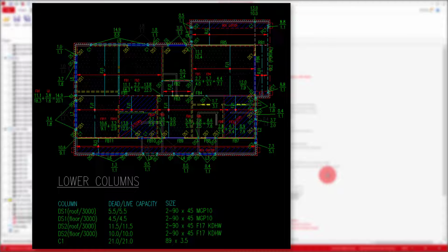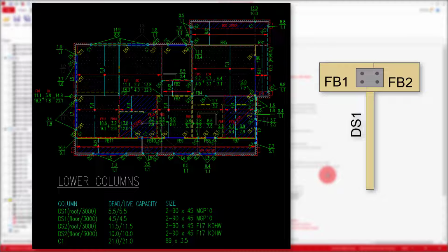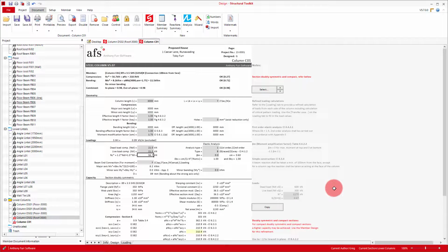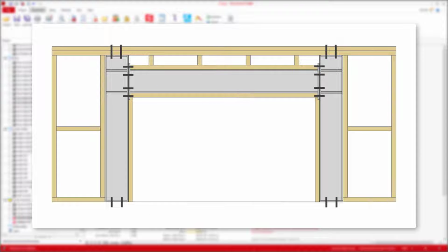In the event that this additional check doesn't work, you could possibly look at the design in more detail. For example, if this load is due to 2 different beams landing on the column from 2 different directions, you could consider the fact that the moments caused by eccentricity may counteract each other. As with most components of this project, there will usually always be ways to refine things down as necessary. At this point, we're now up to our brace frame design, which we will cover in the next video.